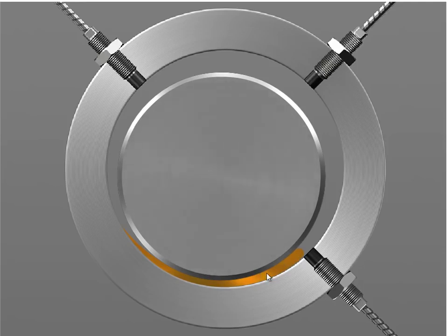So we pump the oil in, that keeps it supported, keeps it stable, keeps it cool, all sorts of good stuff. But unfortunately, if we've got some unbalance or whatever is causing the shaft to move, that vibration doesn't transmit well through the oil out to the bearing, and so therefore an accelerometer may not pick up what's going on. So we use these proximity probes instead. These two probes are sensitive to the distance between the tip and the shaft. As it moves in this direction, this one picks it up, moves in that direction, this one picks it up. The fact is we use it to triangulate.